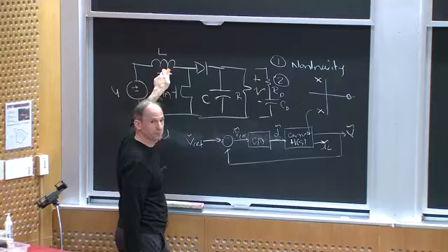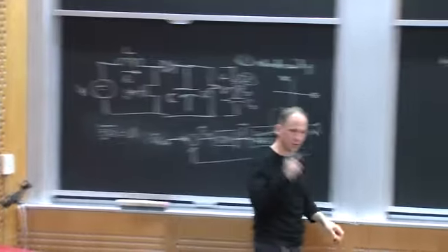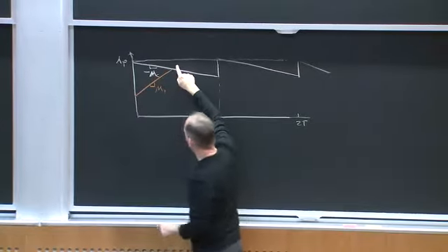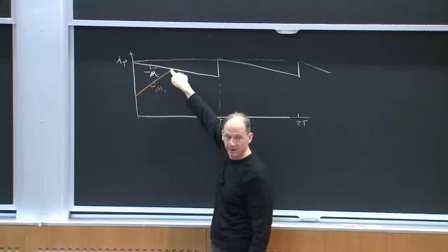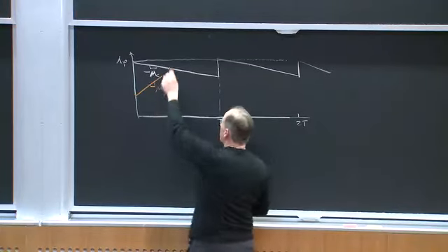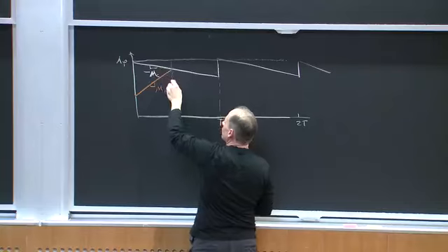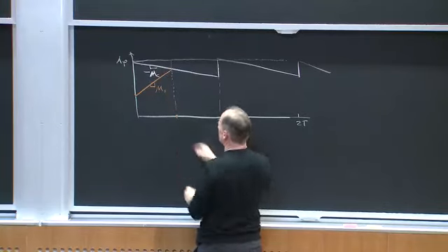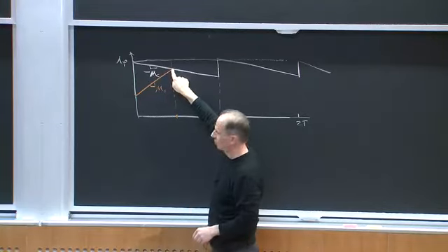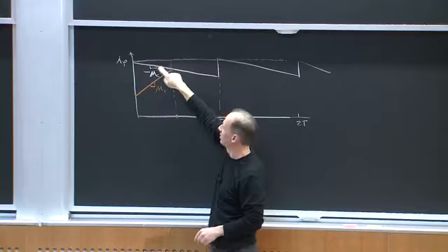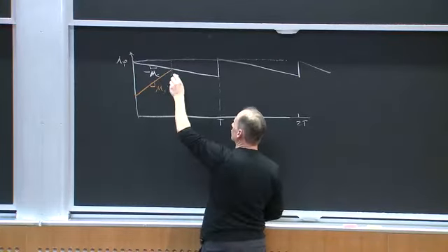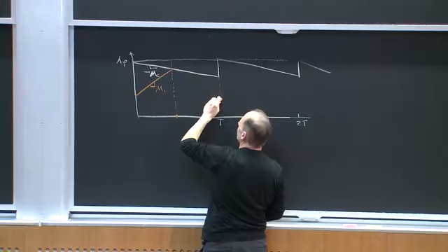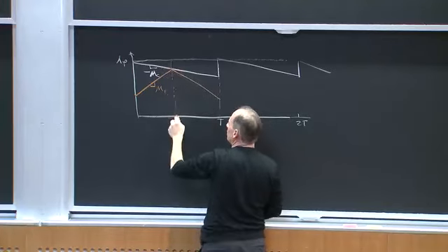and the inductor current ramps up. I'm going to compare the inductor current to IP minus this slope, this pink signal. And when the inductor current exceeds the I peak minus this compensating ramp slope, I'm going to turn off the switch and let the switch current fall like this.